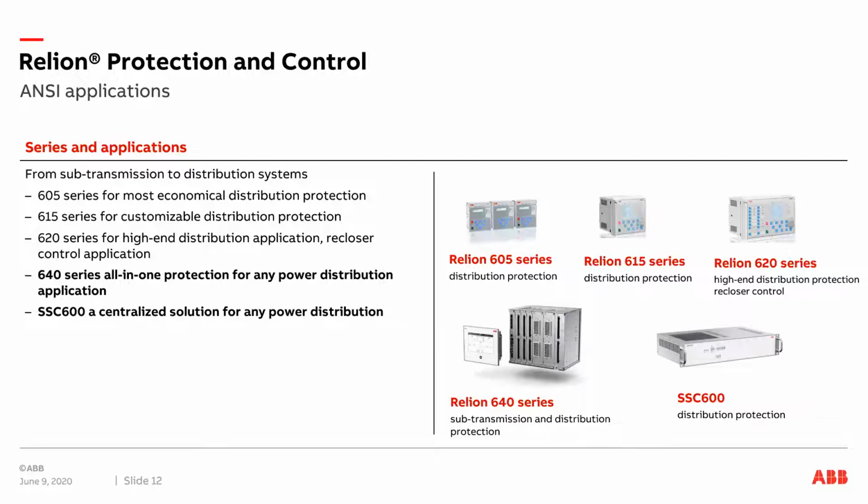So to mention a few things about 615 series. This is one of the popular series of ABB being used globally, and for that matter, any product under Reliant is named with a common naming structure: RE stands for relay, and the third letter will tell you the application. For example, REF means it's a feeder protection relay, F for feeder.